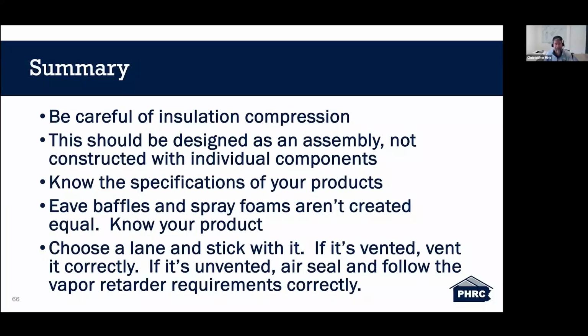This should be designed as an assembly, not constructed with individual components. And that ties into bullet point 1 here. You know, you can't compile that entire sandwich, I'm going to call it, whether it's vented or unvented, open to the lack of looking at that as an assembly, right? You can't just say, I want to use a 2x12 and I want to use some sort of a baffle and I want to use bad insulation, because that might not work. So you have to look at that entire assembly, not individual components within that assembly, outside of the grand scope.